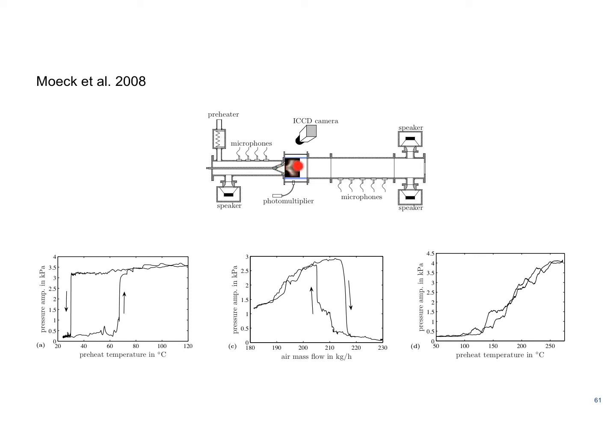the flame actually can go backwards and forward, oscillating in this direction, and you can create huge vibrations in the whole engine, or in this case the whole combustion chamber, but in the gas turbine itself it can be the whole engine vibrating, and this is pretty dangerous.